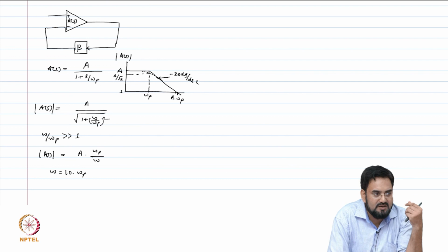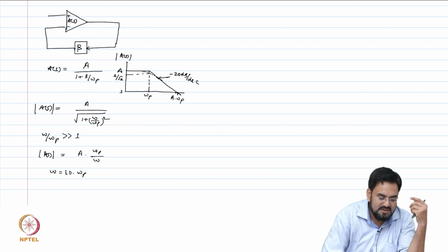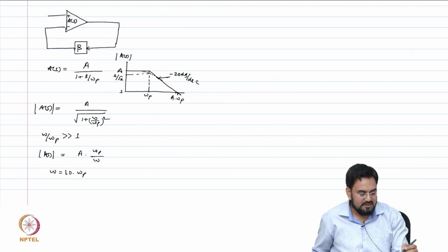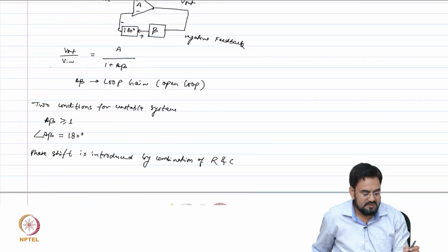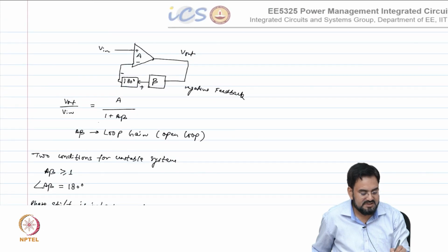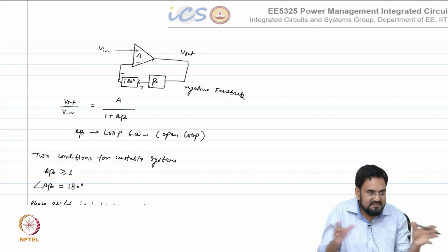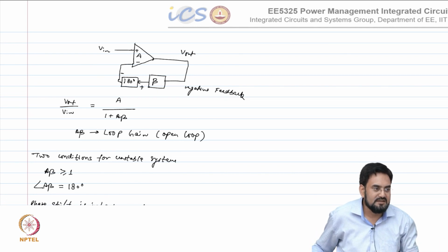And think about, you have a second order system, you put in the closed loop system, so let's say beta equal to 1. If beta equal to 1, then this becomes your loop gain, correct? Now in the closed loop, you have to substitute that A(s) here in both the cases, you have to expand this. So your equation will become a little bit complicated here.